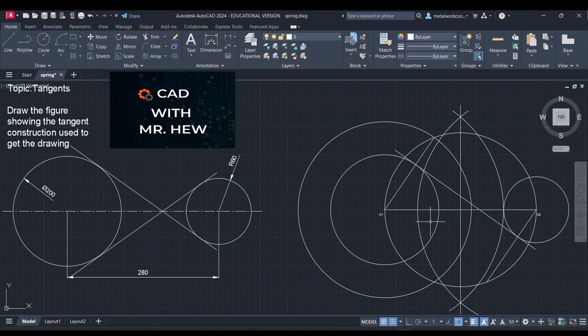All right. So what we're gonna do now, we're gonna draw the line. So here's, okay, we need the tangent. We need the normal. So where this construction semicircle intersects the circle that you added the two radii for, where they intersect, the line drawn from the center to that intersection will be the normal. All right, so we're gonna come here and we're gonna draw the line to there, enter.